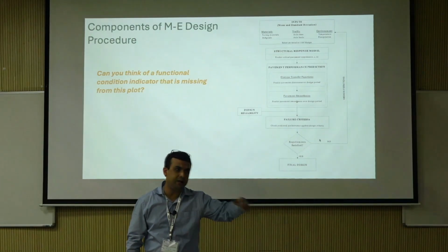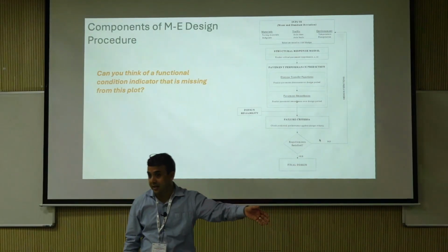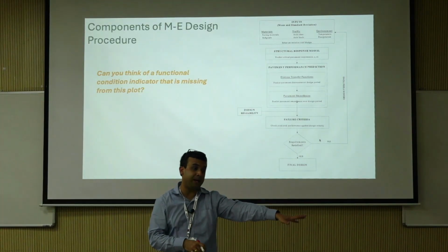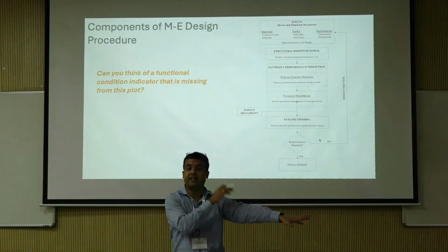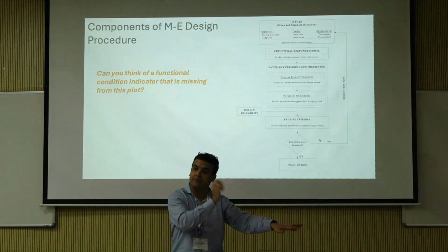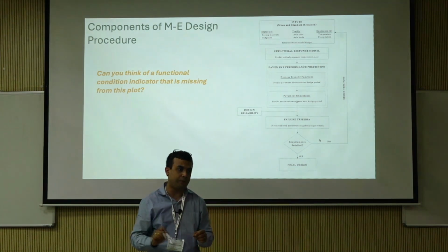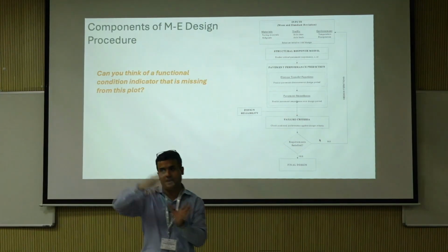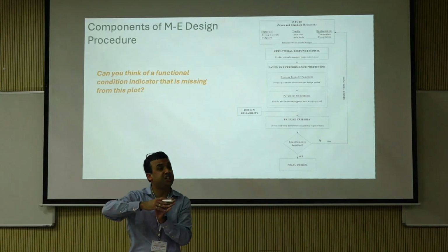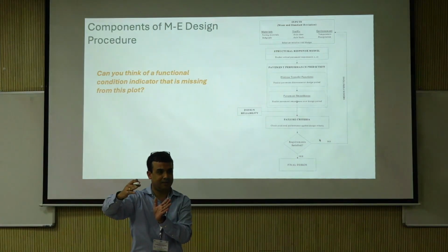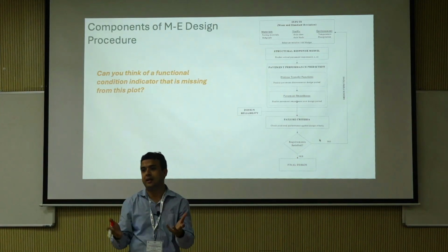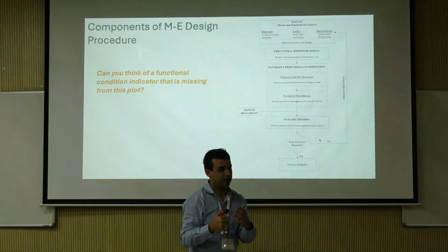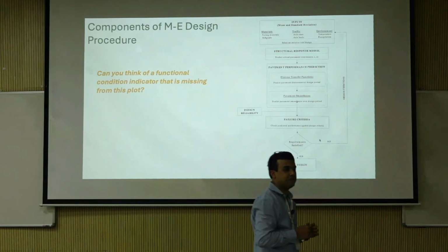So now you have to take your own traffic condition, your own soil condition, your own climatic data. You are going to observe a pavement, saying this is my pavement that is constructed, I am going to monitor its performance, and then I am going to map that, and that is where you do what is known as a shift factor. That shift factor is basically the local calibration. You go from global to local, right?